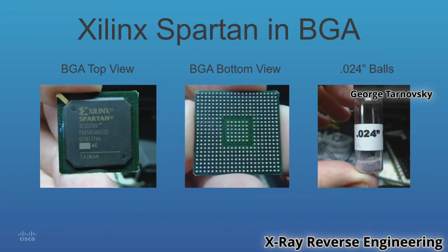So here's a Spartan BGA. In a ball grid array configuration, you can see that the contacts are made using these spheres or balls. This is a jar of them for replacement. When it's placed on a board, you're not going to see anything besides possibly just the edge of the device with regard to connections, maybe. Anything within the inside, you're not going to see using just your visual aids.